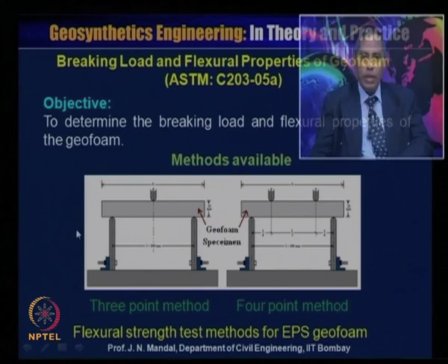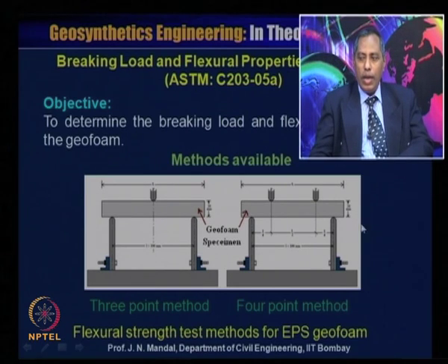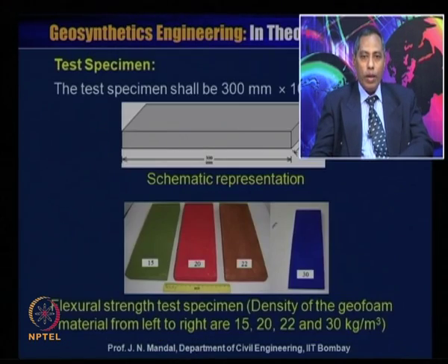Here you can see the 3-point method and the 4-point method. This is the beam, whose dimensions are also given, and you can perform the flexural strength test and calculate the flexural strength of the geofoam material.